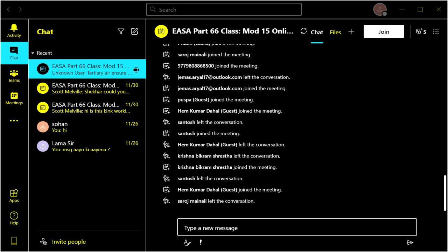So really, all we've got different is a metered spillback and a pressure differential switch. There's not much else different compared to the pressure relief valve system. As it sounds, in the pressure relief valve system, if the pressure gets too high, a pressure relief valve opens. This system doesn't have it; it has a pressure differential switch, a warning light in the cockpit, and a metered spillback. Three different things. That's all there is to it.